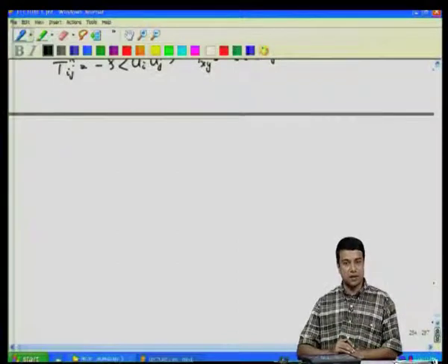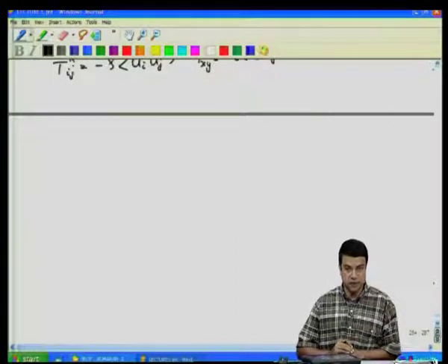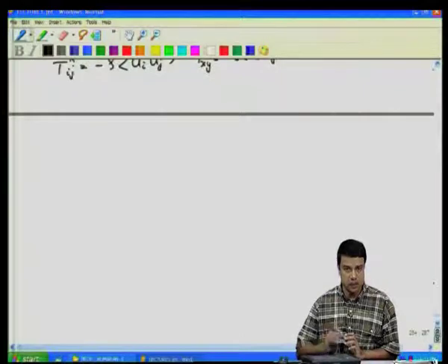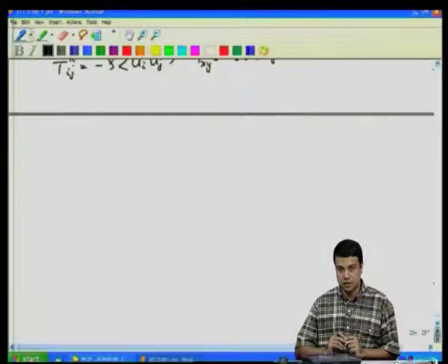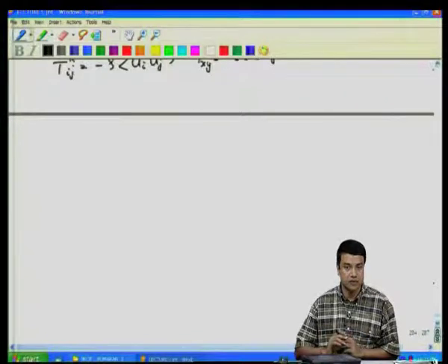So, what is it that generates these fluctuations, these highly irregular fluctuating velocities? Obviously, these fluctuating velocities have associated with them fluctuating strain rates. These fluctuating strain rates, these variations in velocities, are going to result in viscous dissipation. So, if I had a fluctuating velocity, viscous dissipation would tend to slow it down, unless for some reason there is a source of energy which is replenishing the energy of these velocity fluctuations.